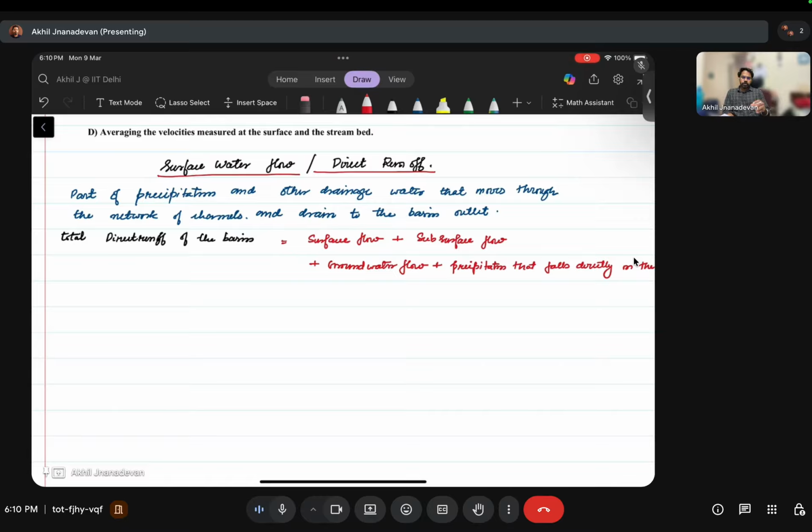and also the surface water flow that is flowing due to the runoff generated by precipitation. And interflow also comes into the picture when there is precipitation or a storm occurring, right? The water gets infiltrated in the unsaturated zone, and in the unsaturated zone the flow will occur along the topography, finally reaching the streams, right? So you have to understand the importance of the groundwater flow, that is the base flow, that keeps the streams still running even during the lean period or the dry periods.